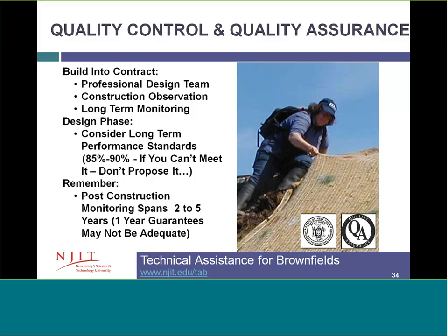So you want to design for success. Be sure to consider that when you're picking the right solution. And then also remember that post-construction monitoring is very important when it comes to living shorelines. One size does not fit all with living shorelines, and also because they are living, it's always good to get back and assess how they're holding up after a year or 2 years.